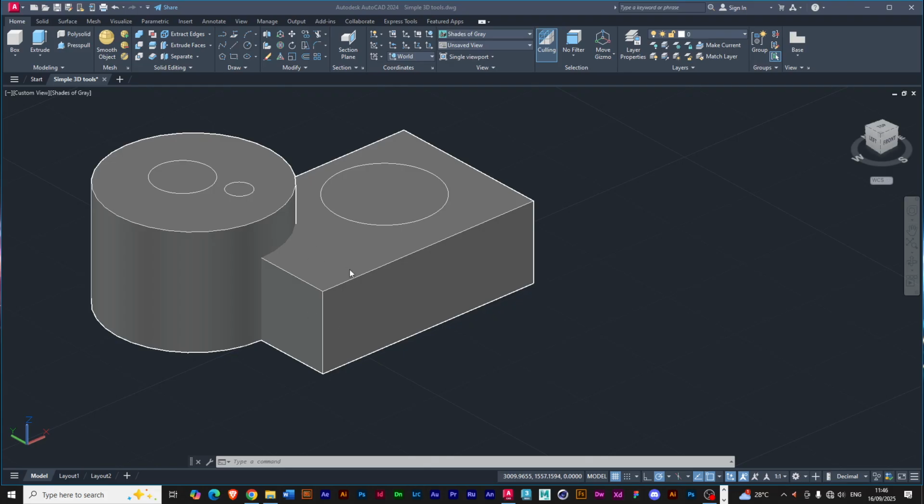So generally, the way normals work is if your objects are not facing in the right direction, when you apply a texture, it will not apply correctly. It will apply like the back of the texture, kind of the back face of the texture. So you always want to make sure all your elements are facing normals. So why I'm talking about normals is the way press pull works. If you are pulling or extruding in the normals direction of the object, it will extrude, create a press pull. But if you go in the reverse of its normals, it will trim off that portion.